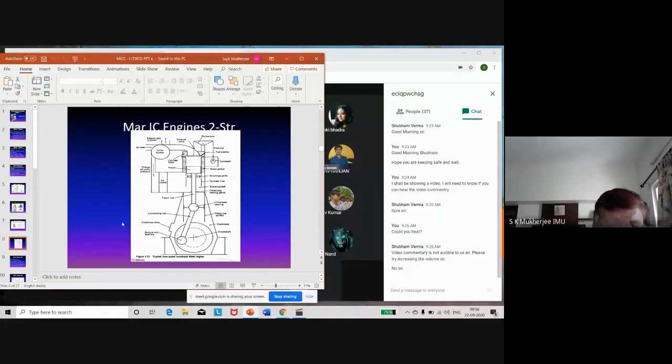So when the oil falls on the steel surface and the steel shaft rotates, it drags the oil down to the underside of the shaft. And this is possible if the viscosity of the oil is right. If the oil is very thin, then the oil will get squeezed out from the sides and will not be drawn in. If the oil is very thick, it will not even go inside that gap. So that viscosity is the most important criterion for the oil which is used for that particular bearing.